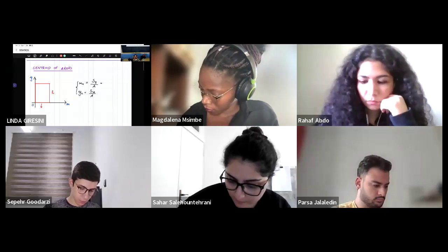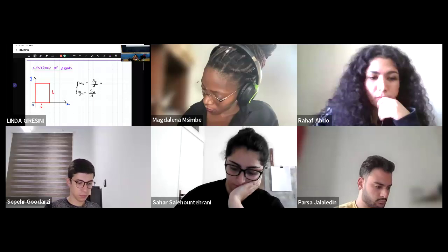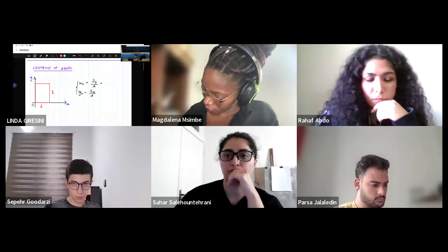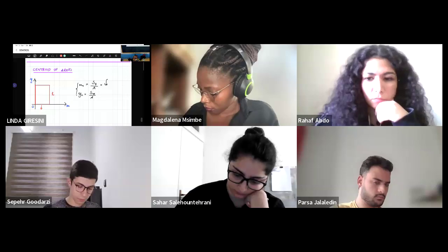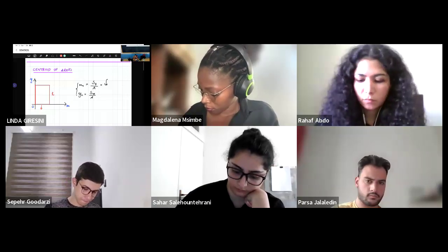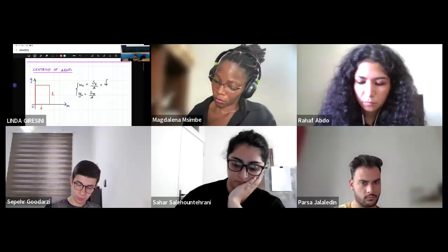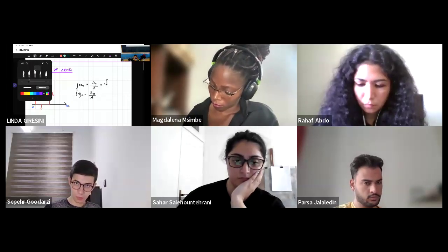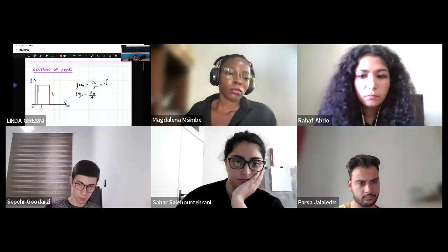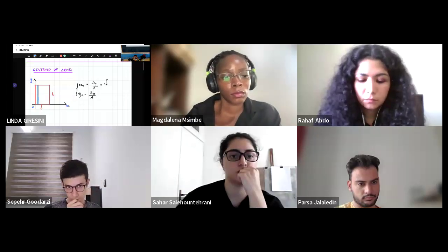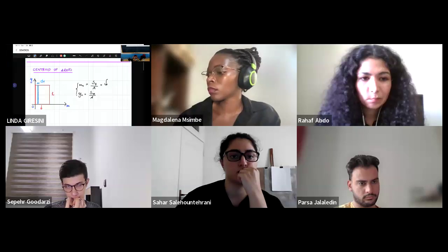So what is the static moment with respect to Y? Since the rectangle is a distributed surface, it will be the integral over the area. This is the definition of static moment with respect to the y-axis. How can we find it? Look, you take a generic strip of width dx.